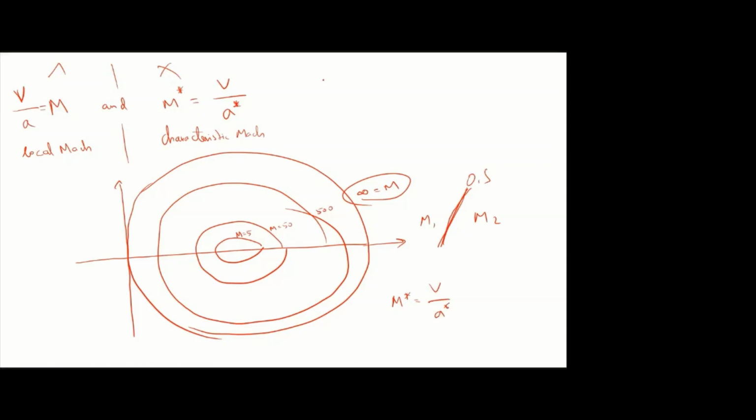So we are going to derive the relation. From the relation, if you take the Mach number, the values vary from 0 to infinity. But if you take this M star, the imaginary characteristic Mach number, then the value varies from 0 to 2.45. So instead of infinity, the maximum we can get is 2.45. So now for this value, we can easily draw the graph. It will be clearly understandable. So for that purpose only, they are using this reference imaginary characteristic Mach number.